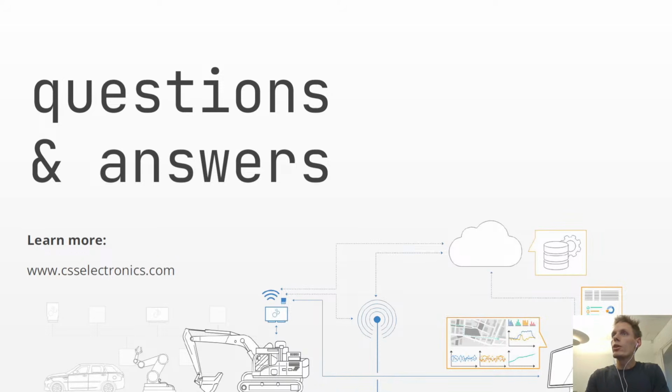Then there is a question on whether you can configure the logger to let it send a service like software version of the ECU to have this info in the same log. And I think if I understand this question correctly, then to some extent, yes. An example of this is that you might set up a transmit message or a sequence of transmit messages that the device will fire after a power cycle.